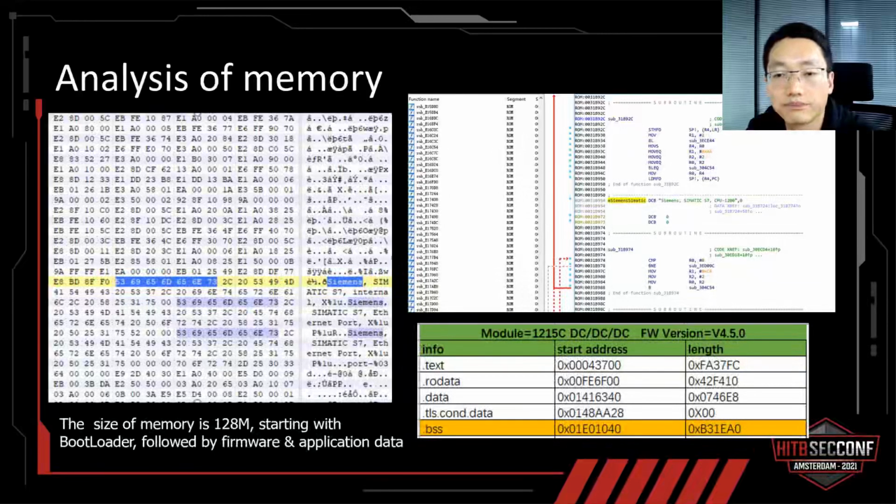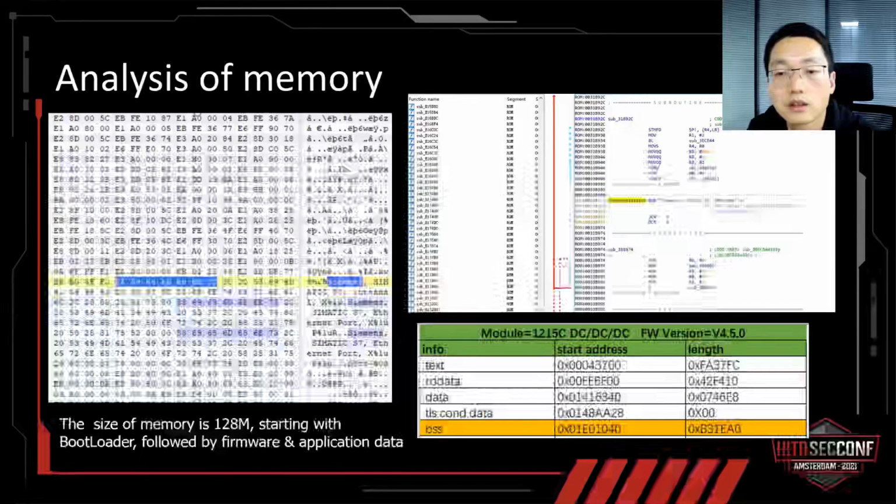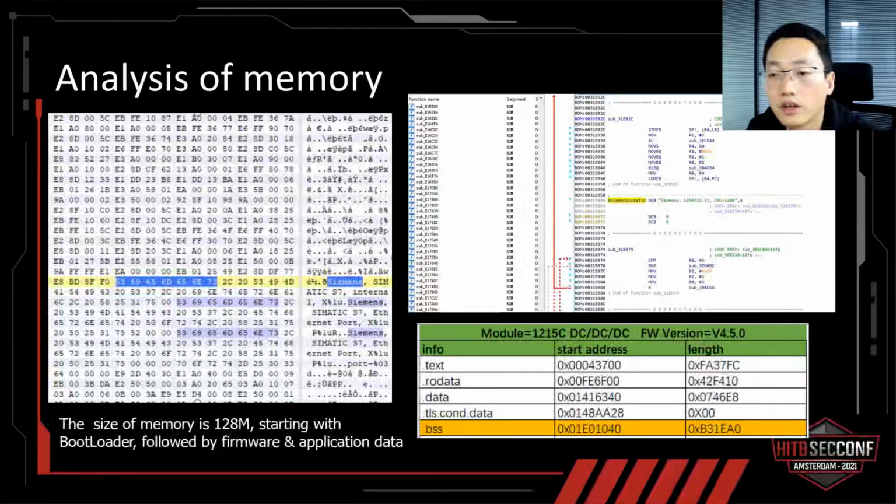We analyzed the latest firmware version of S7-1200 in detail, from May 2021, and obtained its code segment, read-only data segment, and the starting address and length of the data segment. The corresponding decompiled pseudo code is also obtained by loading the code segment content using IDA.